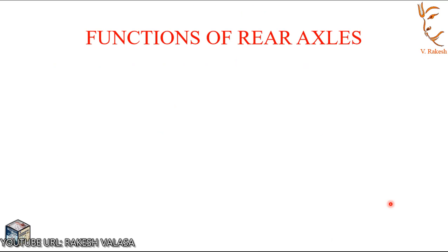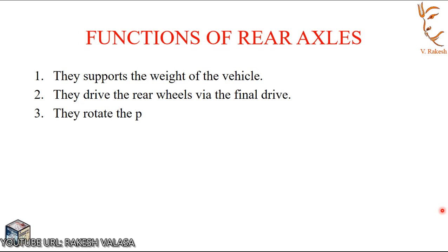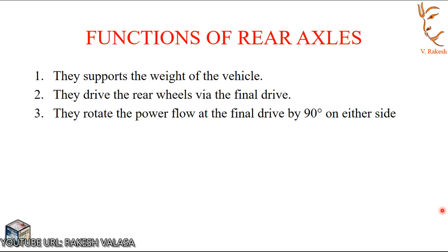Let us see the functions of rear axles. The main function is they support the weight of the vehicle. They drive the rear wheels via the final drive. They rotate the power flow at the final drive by 90 degrees on either side for driving the wheels.